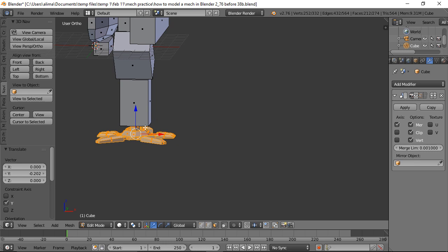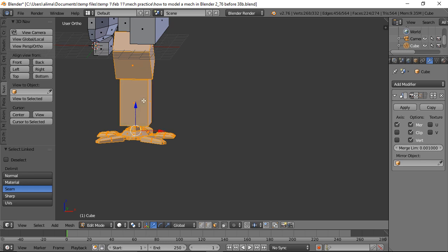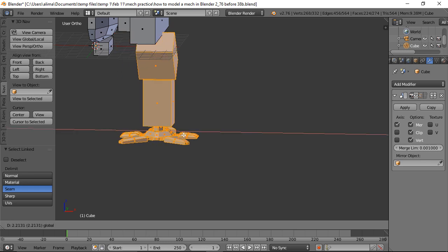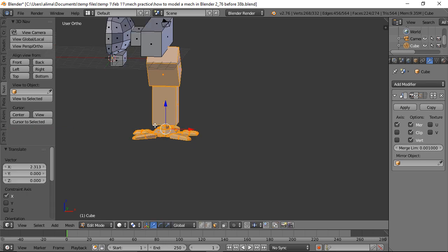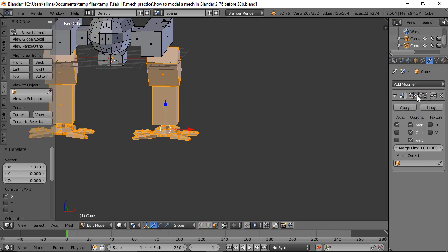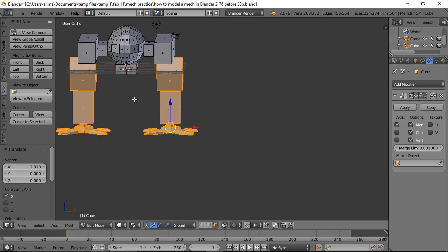Okay, then with that foot selected, I'm going to select here. I'm going to press L. I'm hovering here, so I pressed L. I'm pressing L here. I'm going to pull this to the side some, just because I don't want this geometry from this foot. See that even though we have the mirror modifier off, see that the half right here, so I'm just trying to give some distance there. So now I'm going to click this eye, which now we can see our mirrored geometry there.